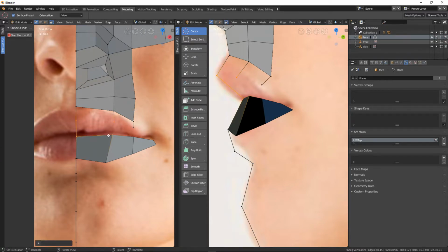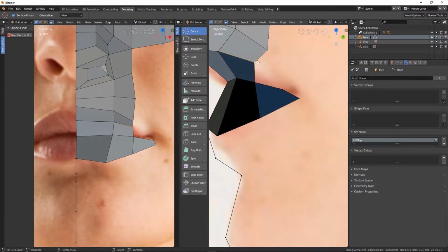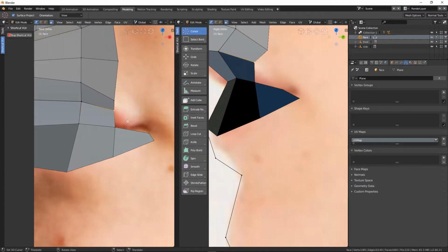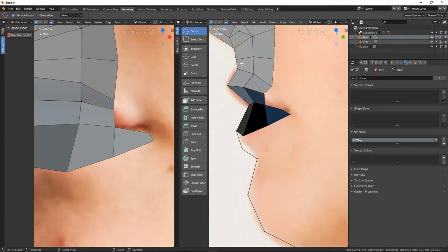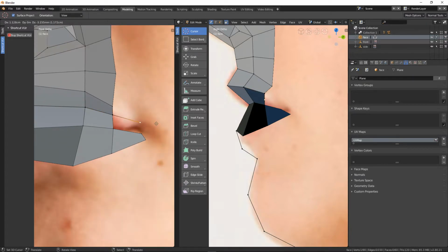so now we can start putting in these faces and filling this in. So you can see that they've changed color here compared to the rest, and that's to do with normals. So every face has a direction, so it's either facing towards us or away from us, and Blender has decided that these are facing in the opposite direction to the rest of them. We are not going to worry about it now. We will fix it before this session is over, but it's a simple function to flip the normals.